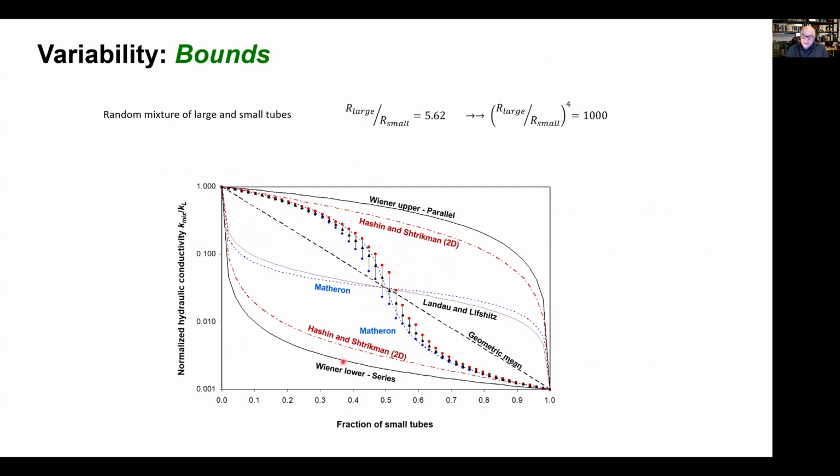because of the prevalent role of large, interconnected pores on permeability, the uncertainty on permeability and hydraulic conductivity can be quite large. So we cannot automatically assume the various averages. Sometimes we have to consider the upper bounds and the lower bounds in our analysis.